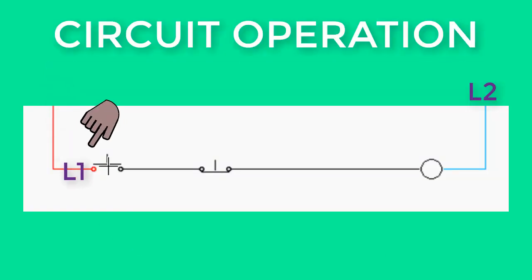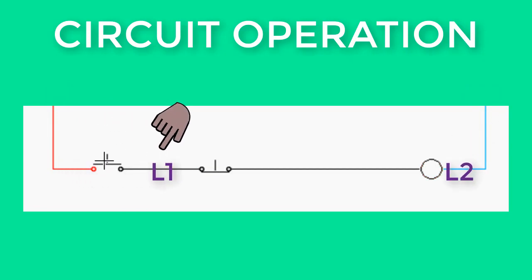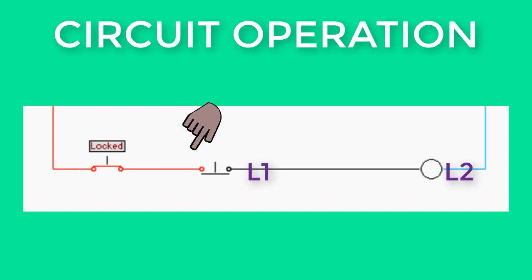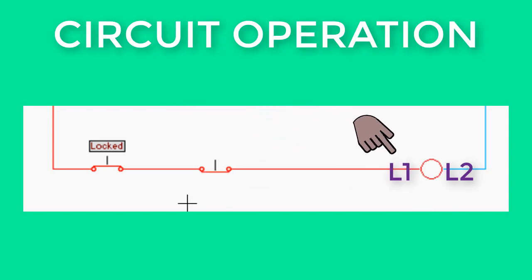The circuit shown is a typical ladder logic drawing. Line L2 is typically connected directly to the coil. All control switching devices to the coil are typically wired with line L1.